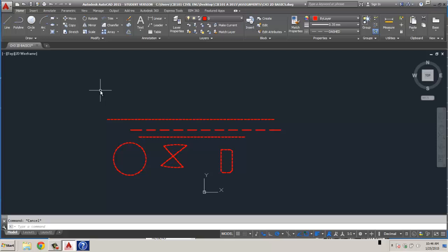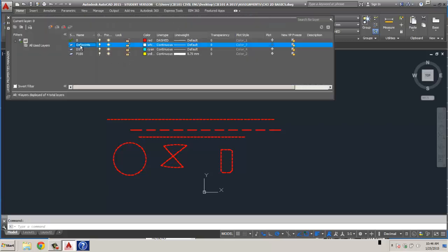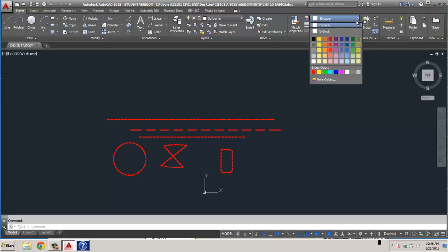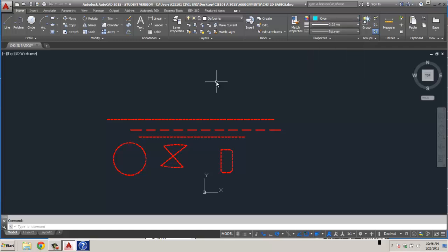Okay, beyond this, we get into some text placement tools. Let's just briefly look at text, and I'm going to change our layer to something else. We'll go into definition points. Make that an active layer. You see the check mark in front of it, that means it's an active layer. We're going to work in by layer, and we want our color to be light blue.